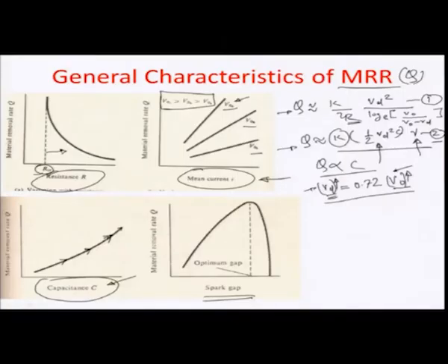Therefore, if VO is higher, it automatically means that we are operating at a higher gap discharge voltage Vd, and Vd being proportional to Q means that a higher operating voltage, meaning a higher discharge voltage, would have a higher machining rate or material removal rate in comparison to a lower operating voltage VO1. Thus, this different range.